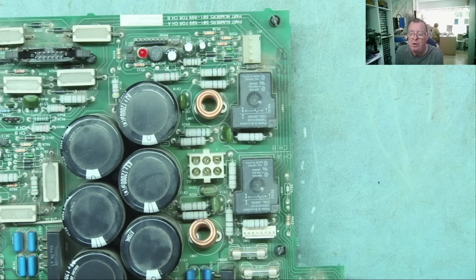A very common failure with switches is in vintage audio amplifiers. These are home amplifiers mainly that have multiple inputs, so you can switch between tuner, CD, phono, auxiliary and various inputs. They have large multi-pole switches in them, sometimes with 12 poles, can be a lot of poles, and on those sort of amplifiers also the mute switch may have many poles, and they also tend to fail. Now they fail with age, and if you open one up they're all blackened inside.